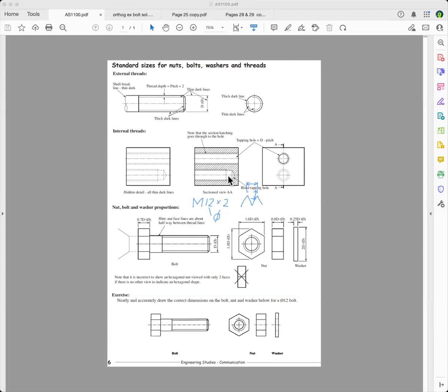You just show a section like this, but I have never seen you do a section. You won't be asked that there. So make sure you know how to do a section. So here, you've got thick, dark lines at the end. You're looking along here and you're drawing what you see there.